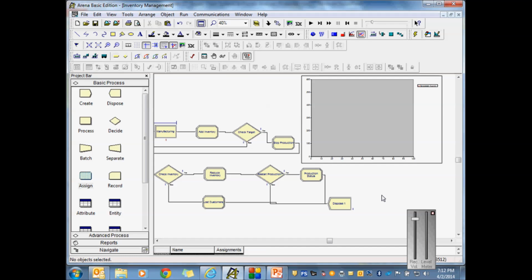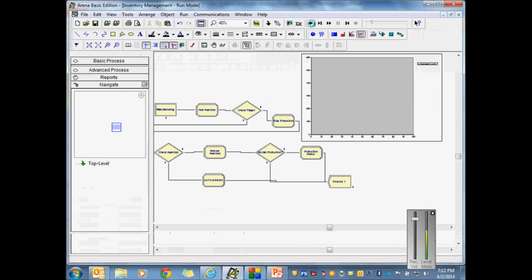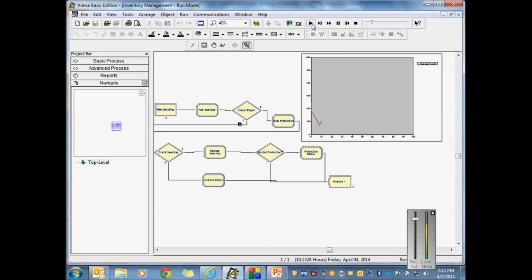So now I'll be able to get a gauge on what my inventory is doing as I run this. If I go here, you can see that we used up some inventory. As soon as we dip below 150, what did it start to do? Started to go into production. Okay. Now, good, bad, and different. We want to minimize the amount of work in process we have, but it looks like we're keeping up with demand. We don't have any idle time on manufacturing. It looks like we're always manufacturing, as can be seen up there.